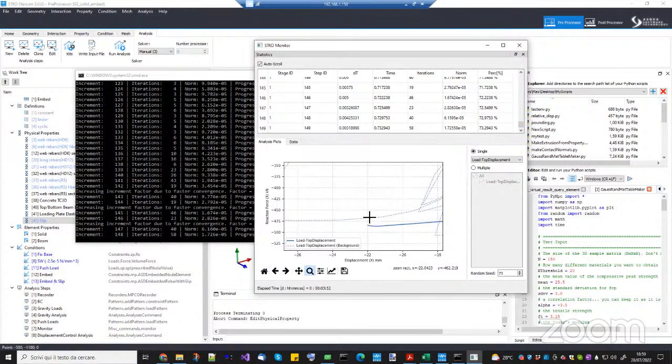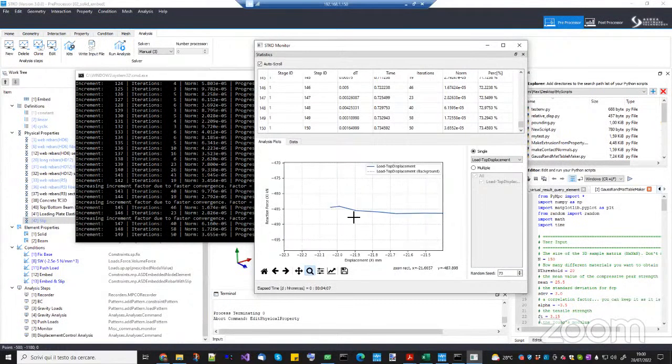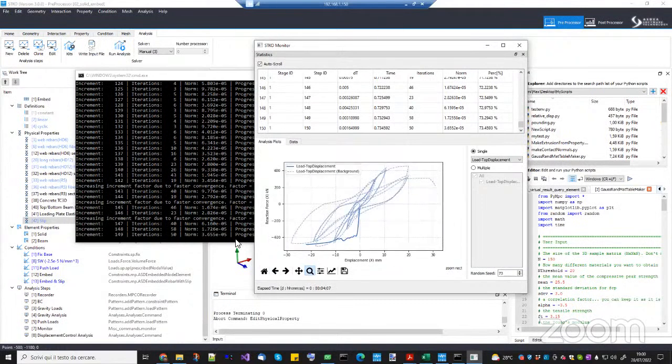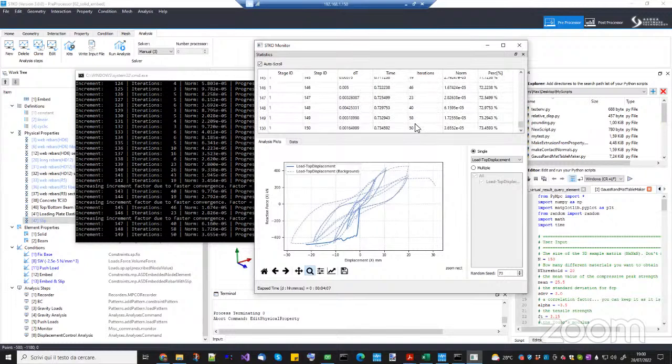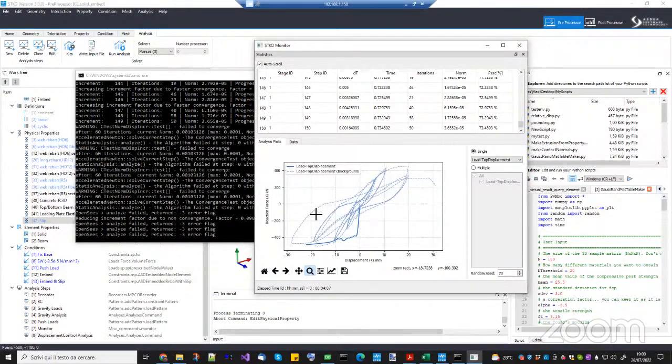As you can see, when using the Implex algorithm, you have a lot of advantages. As soon as you put a standard material model with softening, but without any special algorithm, even these small jumps here will create a lot of issues. The problem is that the analysis time will grow a lot because you move from 3 to 4 iterations up to 60 iterations, so the computational time will be much more. So actually, step by step, we will try to implement the Implex algorithm also on other material models.